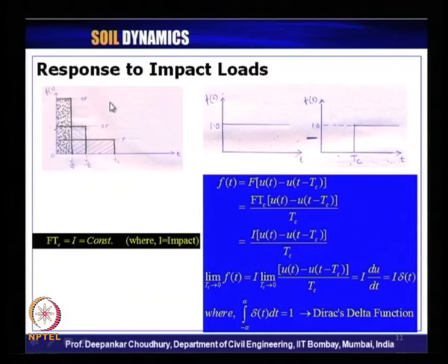After that, we have seen the response to impact loads. Impact load we can compute by keeping the area under the f of t curve constant. What we have seen is that f times t c under this curve we are keeping constant. So, that is the concept of impact load. The time for which it is acting is very small. However, the magnitude of this load is pretty high.